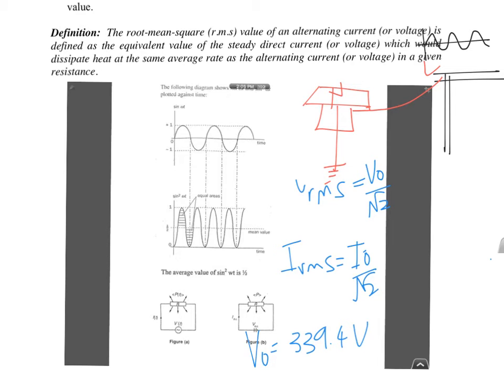Alright. So don't forget, stepping up the voltage is not just to reduce power loss. Stepping down is not just for safety, because some appliances or electric components need different voltages to run, and it's easy if you use AC. You can just switch between any voltage that you want easily using a transformer. That's why AC is still used in the whole world.